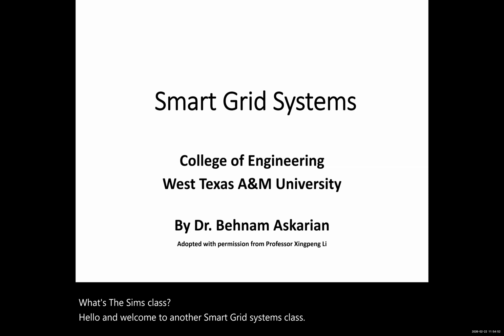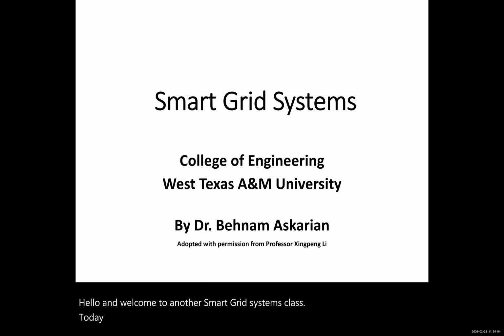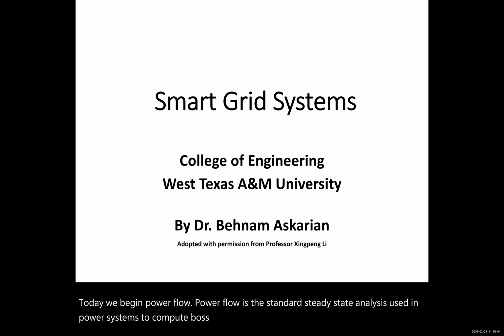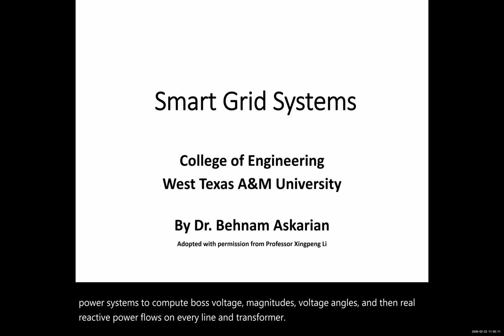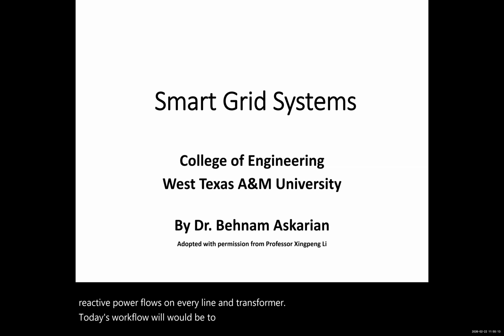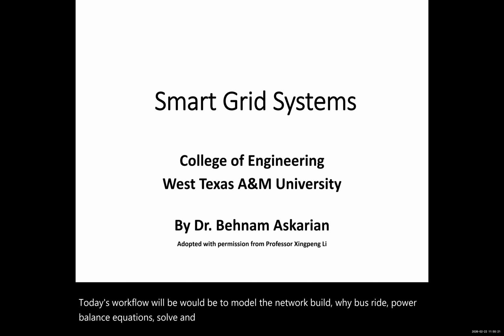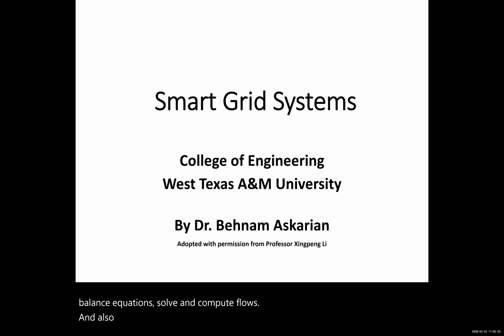Today we begin power flow. Power flow is the standard steady-state analysis used in power systems to compute bus voltage magnitudes, voltage angles, and then real and reactive power flows on every line and transformer. Today's workflow would be to model the network, build Y-bus, write power balance equations, solve and compute flows, and also losses and violations. By the end, you'll understand what the solver is doing and why.